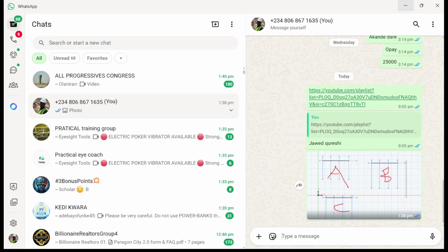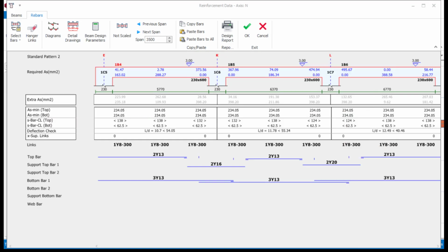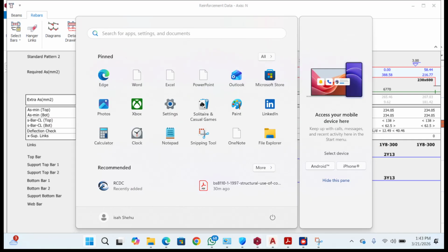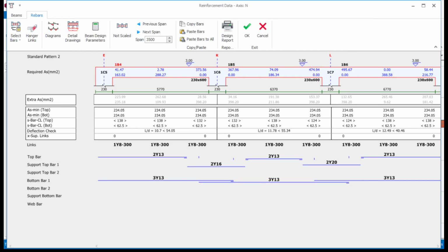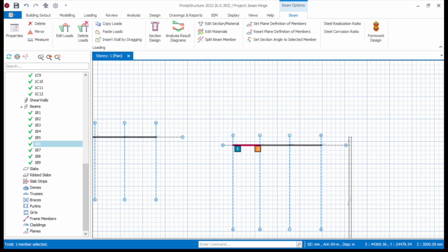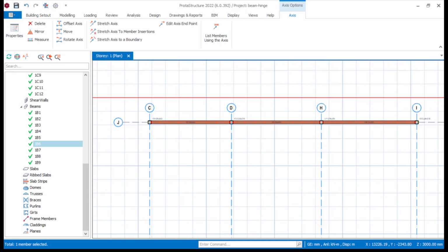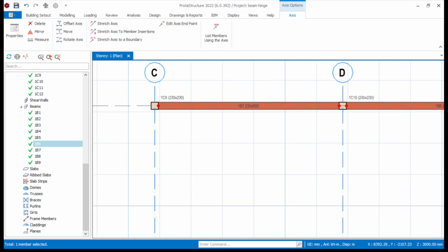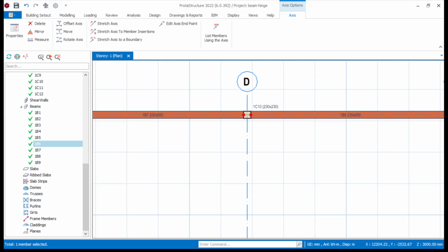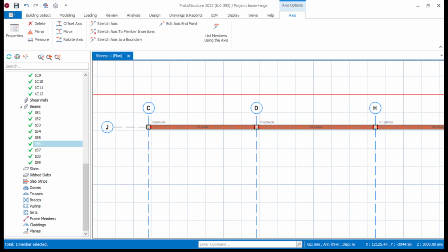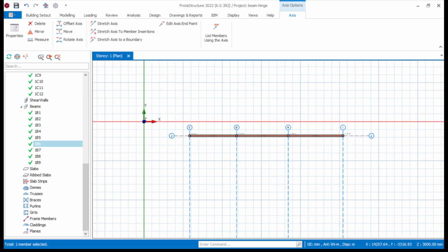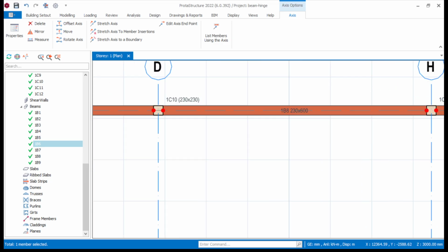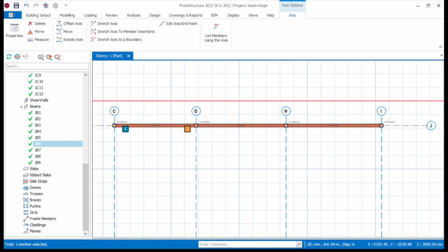So let's go to C now. Like I said, C, you do not do for a reinforced concrete structure. We do C for steel structures. That is when we want to do the structural framing and we want it to be a pin connection. That is when we do something like this, whereby you do moment release, or you hinge the beams at the middle, that means the intermediate beams. You hinge it. This is not done in a reinforced concrete structure. I repeat again.